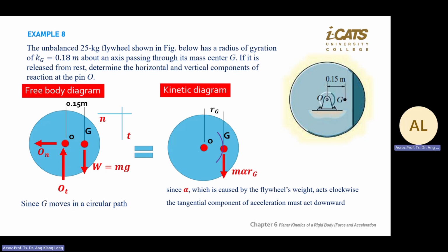So you convert your tangent acceleration: a equal to alpha R. You write MAT also correct. It's just that you need to apply the alpha. There's another rotational parameter, which is called Ig alpha. You take Ig, the moment of inertia, multiplied by the alpha, and you get rotational force.